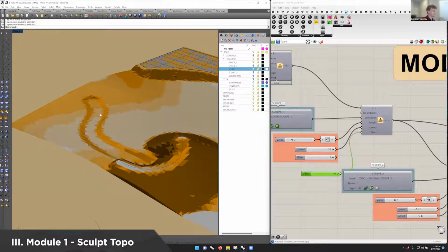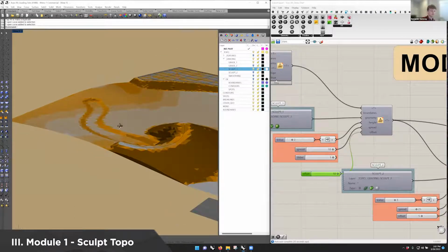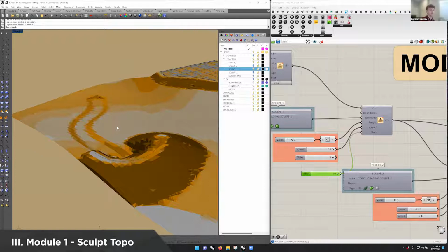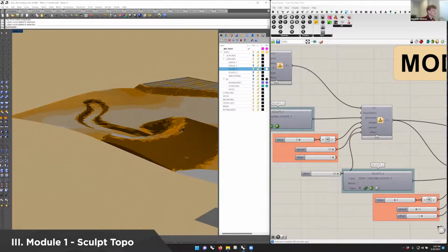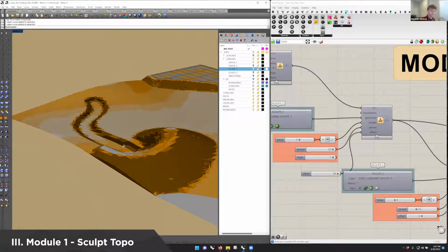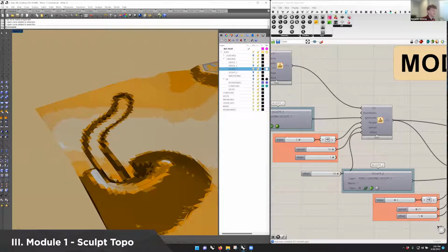Yeah, so this way, if I know that the hillside is sloping down already, I don't need to create any artificial down slope. So I can just use the Sculpt tool to drop the topography down as it exists another 2 feet, or even more if we'd like. We can drop it down 5 feet or raise it 5 feet if we want to. And it will just give me my slopes, and this is processing live to see.